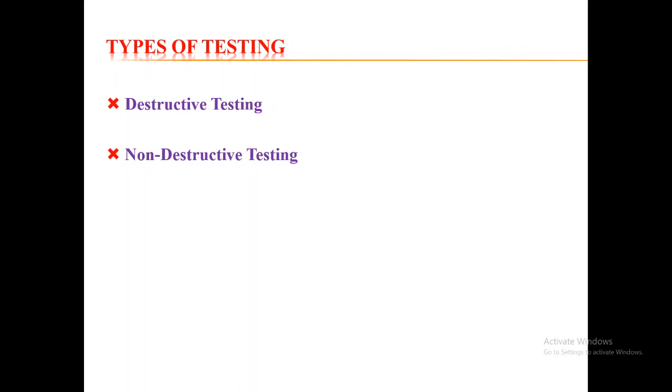Whereas in case of non-destructive testing, the testing engineer has to take care that the insulation should not be damaged permanently. Like the partial discharge test and the tan delta test are normally put into the category of non-destructive testing, because the voltage applied during these testings is not capable enough to create any permanent damage to the insulation. So these are the two types of testings which you can usually see in the high voltage laboratory: the destructive test and the non-destructive test.